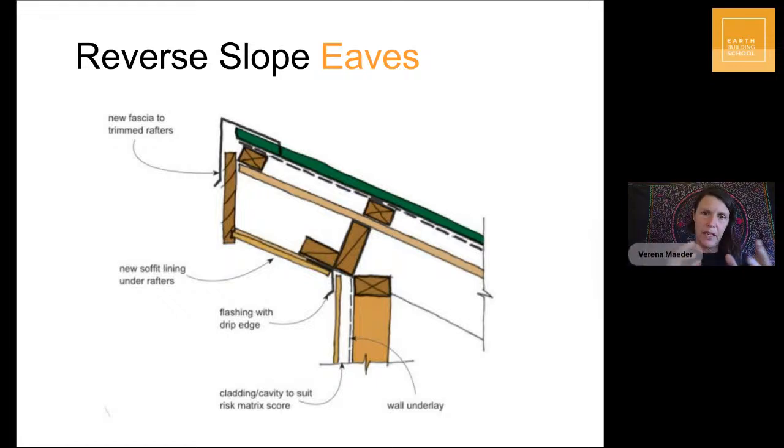When you're specifying the timber sizes for your roof members, there's always a mention of the type of fixing that you need to put in, and you need to follow that, because wind uplift in high winds is a serious thing. So there's always the situation where roofs blow off. You need to take this seriously. So follow the standards according to your wind zone, and I would even encourage you to overachieve a little bit with this and go for the next wind zone up, because wind strengths are picking up in most locations with changing climate.